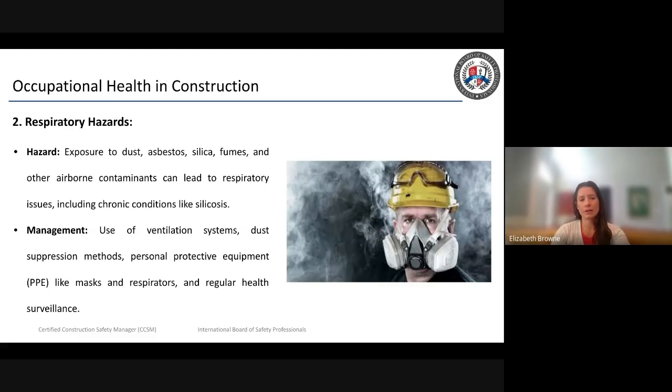And it may require you to have medical surveillance monitoring for your workers where they have chest x-rays, having continuous health surveillance and monitoring on the chest, lung x-rays to ensure that the worker's not being exposed to enough silica that's causing what looks like could lead to silicosis.